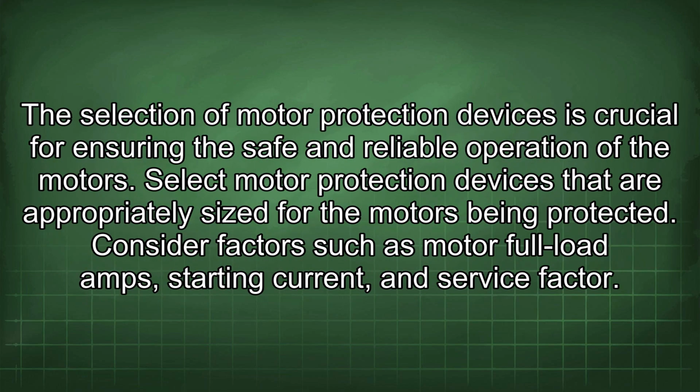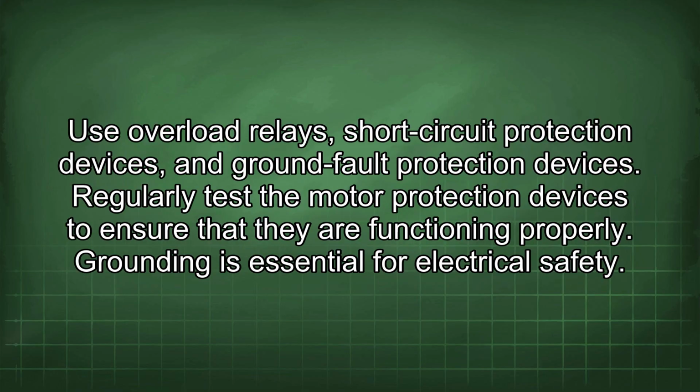The selection of motor protection devices is crucial for ensuring the safe and reliable operation of the motors. Select motor protection devices that are appropriately sized for the motors being protected. Consider factors such as motor full load amps, starting current, and service factor. Use overload relays, short circuit protection devices, and ground fault protection devices. Regularly test the motor protection devices to ensure that they are functioning properly.